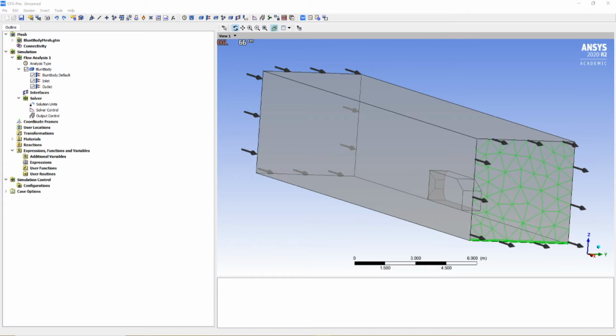This boundary is an approximation that may not accurately represent the true flow conditions. By using a free slip wall boundary, the flow modeling will be less accurate, but the computational grid size can be reduced by modeling less surroundings. So this basically allows us to use a smaller domain. And in this case, we're modeling a wind tunnel experiment, so the geometry would match the size and shape of the wind tunnel and use no slip walls.